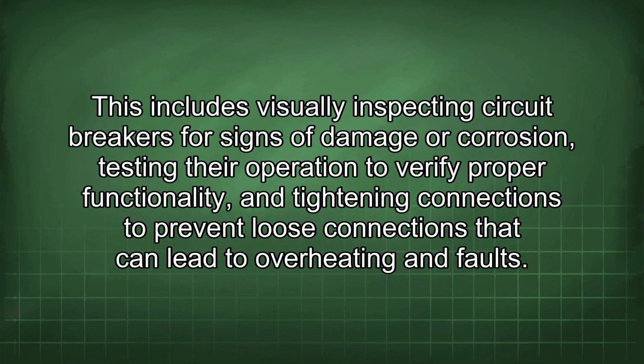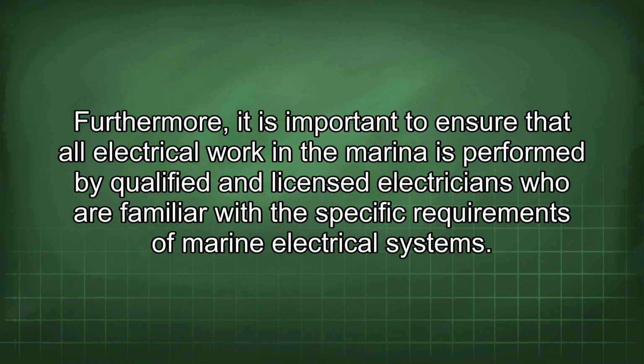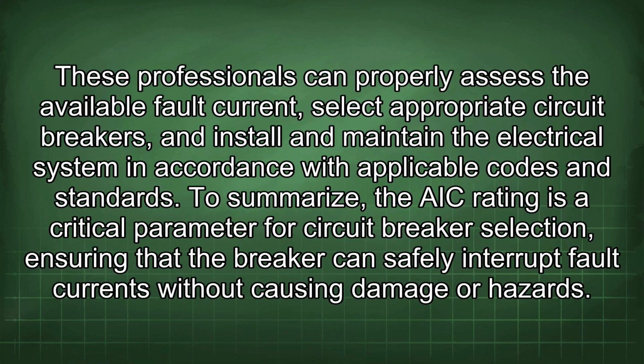This includes visually inspecting circuit breakers for signs of damage or corrosion, testing their operation to verify proper functionality, and tightening connections to prevent loose connections that can lead to overheating and faults. Furthermore, it is important to ensure that all electrical work in the marina is performed by qualified and licensed electricians who are familiar with the specific requirements of marine electrical systems. These professionals can properly assess the available fault current, select appropriate circuit breakers, and install and maintain the electrical system in accordance with applicable codes and standards.